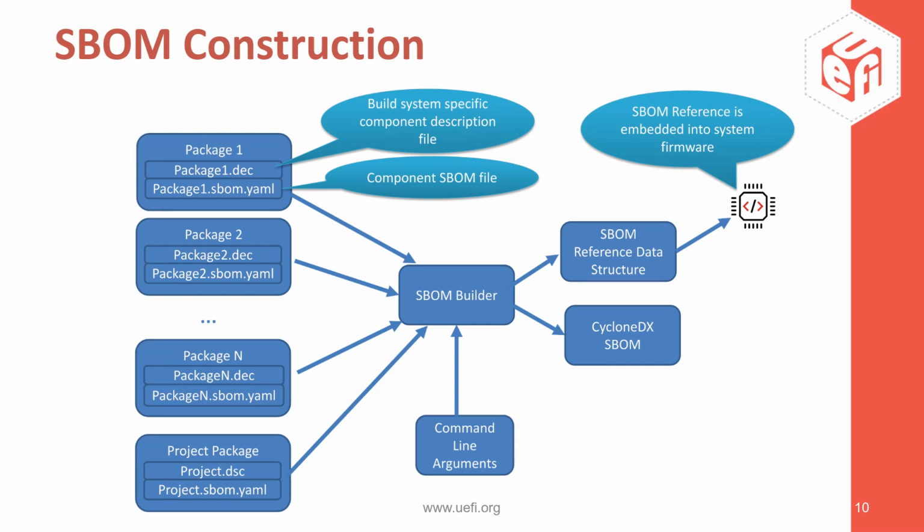And in modern firmware, the mapping of source to binary is quite complex, especially, as you know, EDK2 is very flexible, and a lot of this flexibility comes from libraries. Most of the platform customizations are performed via libraries. For example, the OEM may create a single library instance, but it may end up in 55 different binaries if this is a heavily used library.